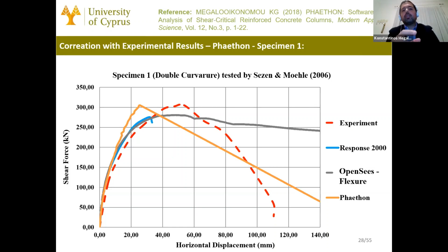only to consider shear flexure interaction as in OpenSees with zero length elements and limit state materials at the bottom. So this is the one way, or to add the shear mechanism using the wrapping aggregator. Aggregator, exactly. Okay.